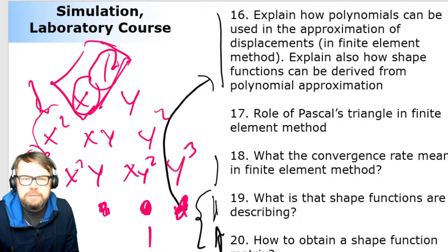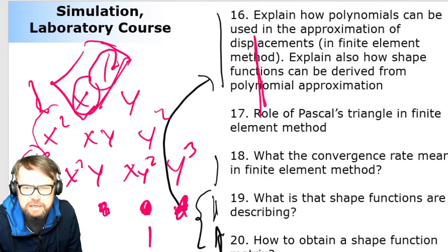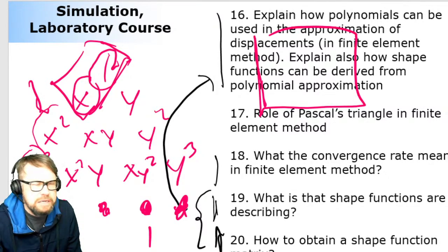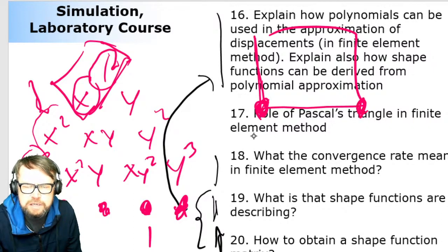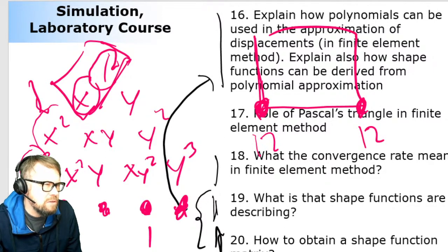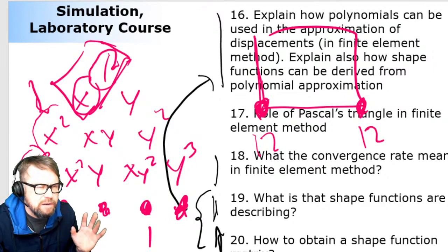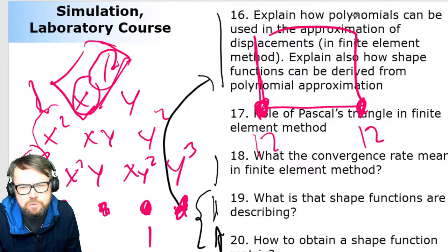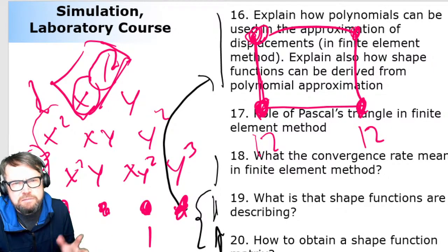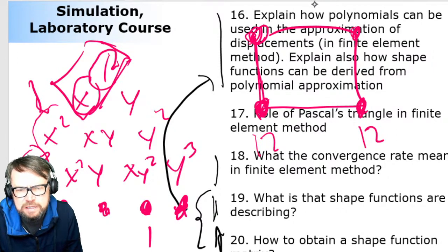It was like this rectangular shaped plate element, and each one of the nodes consists of 12 degrees of freedom. 12. It's possible to make something like that. It just means that it has a little bit harder physical interpretation of what these 12 degrees of freedom mean. But they simply mean fiber deformation, internal fiber deformation within the plate.